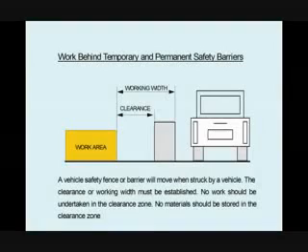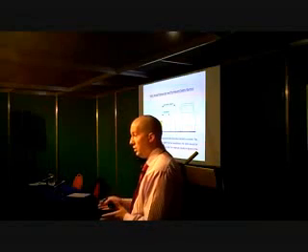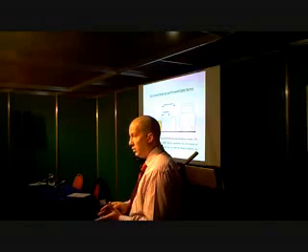I'm going to look at that one in detail and then briefly go over a couple of others over some photographs. So first of all, when you work behind permanent and temporary safety barriers, they have a containment value, they have a deflection zone referred to as either the working width or the safety zone behind that barrier. Okay? So if that safety barrier gets hit, it will move. Okay? It's designed to move in and contain the crash.